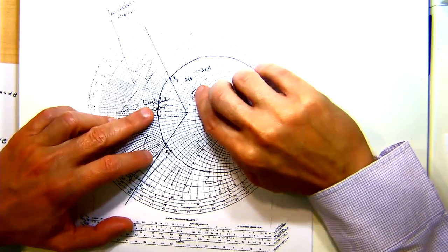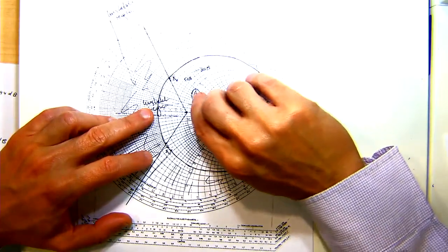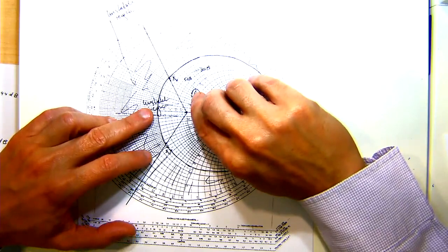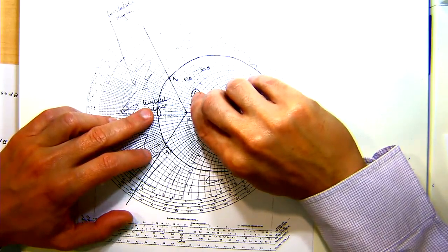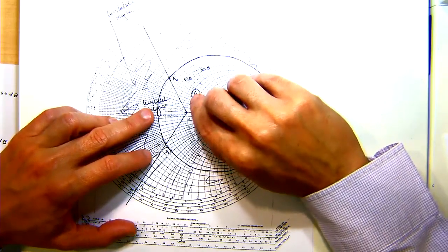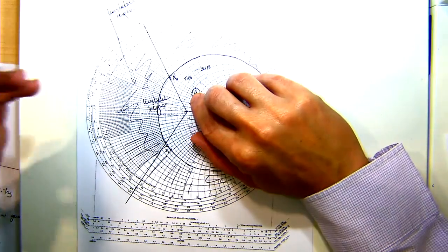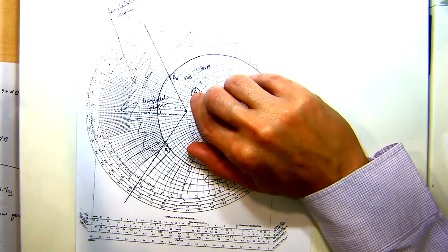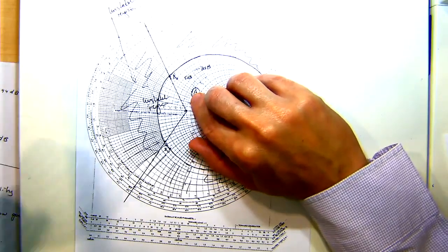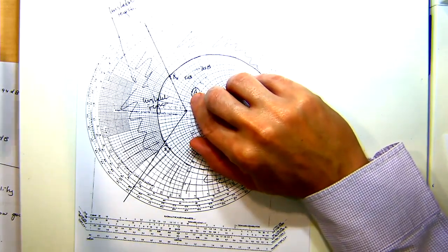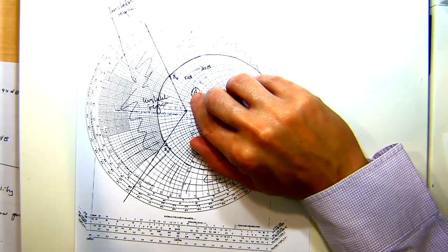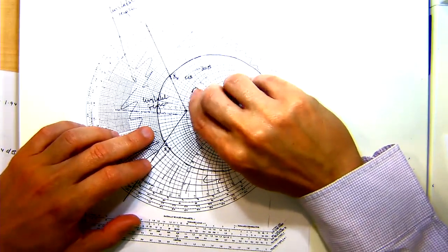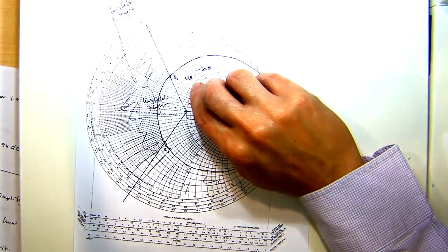In this particular case, once you draw your 3 dB gain circle, you'll find this point A has the greatest real part, and that is the point which gives you the greatest degree of stability. So if you were designing your network and you wanted an amplifier with 3 dB gain, but as stable as it can be while still giving 3 dB gain, you'd try to get around this particular point.